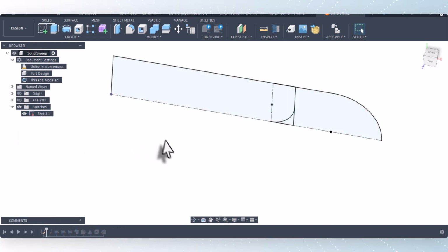And so I turn on my sketch. So on the lathe, we would turn the cylinder and put the fillet on the end. Now I've gone ahead and put the sketch for the end mill in here as well. And so then the next thing I'm going to do is go ahead and turn that diameter. So also I'm going to put the path in here for this end mill, but we'll come back and look at that.